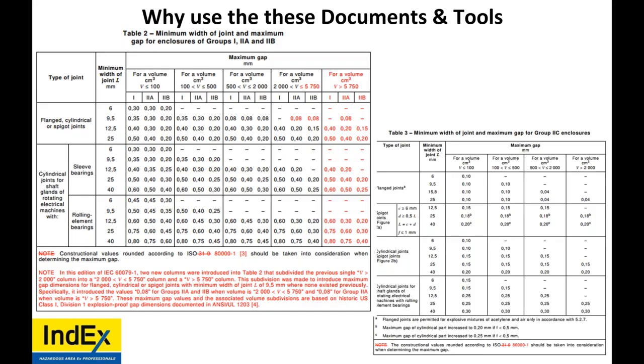My understanding is a plant can choose to install Article 501 or 505, but they should mix equipment to Article. I think that should say they should not mix. So yeah, there's NEC 500 and 505. NEC 500 is classes and divisions. NEC 505 is classes and zones, AEx. So one would be explosion proof 500 and the other one would be flameproof 505, but it's American Ex, AEx.